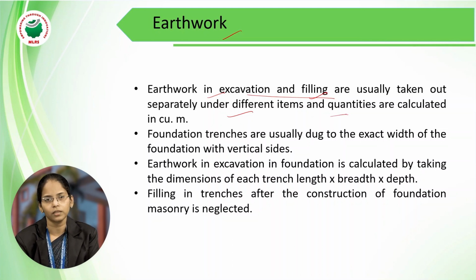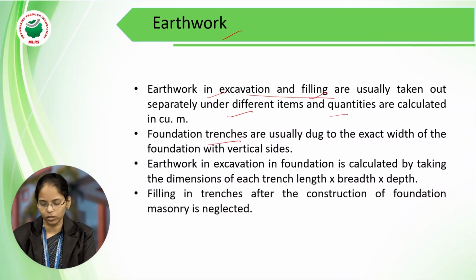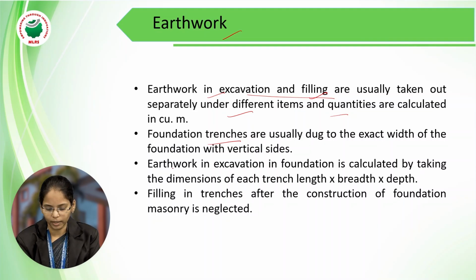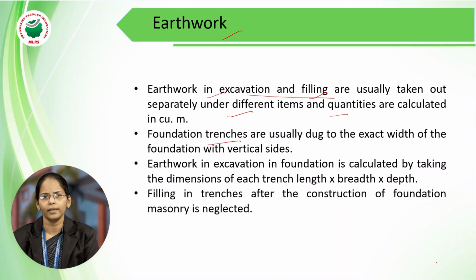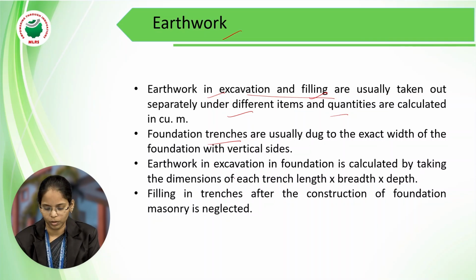So we need the quantity and how many items we use in excavation and filling. Next, trenches. We need to dig the trenches to the exact width and length which we require for construction of any structure based on the foundation. And next, the vertical height or depth varies based on the structure specifications.